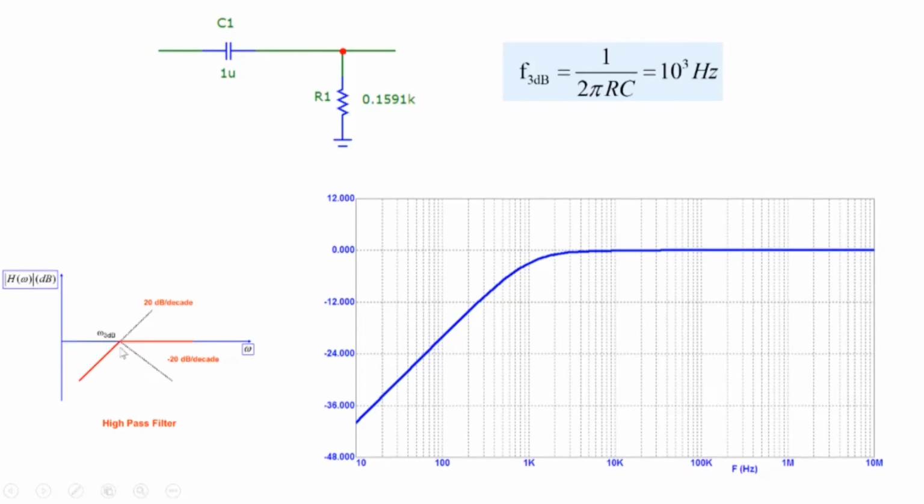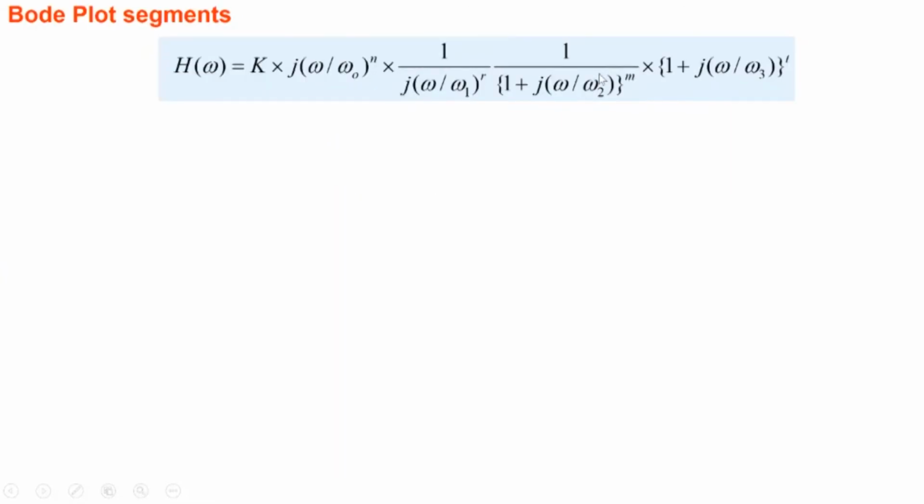And we said that we are not sketching things very well at this particular point here. So you can see that our cutoff frequency is 1K here. So at this particular point, what will be the magnitude here? Minus 3 dB. Please verify it, that if I substitute numbers there, this will be minus 3 dB at this point. That's why many times we call these frequencies 3 dB frequencies, cutoff frequencies. They are the point where it's 0 dB, and then at this particular point becomes minus 3 dB. This is where we have this 1 over 2 pi RC.